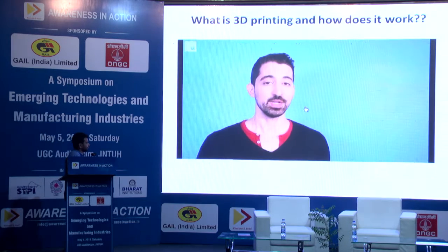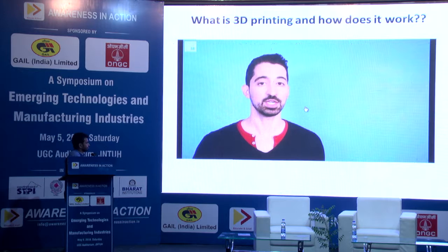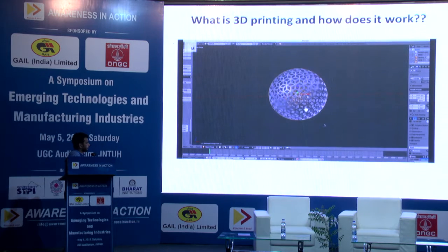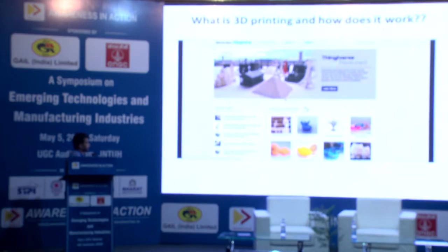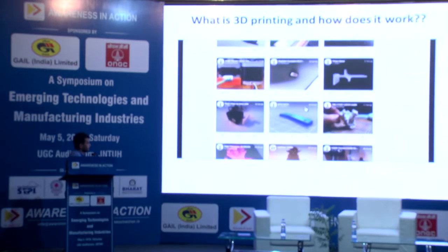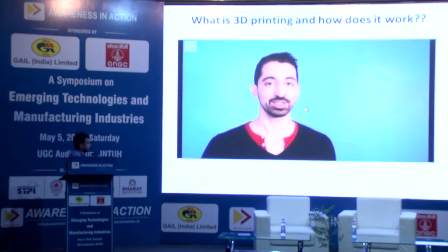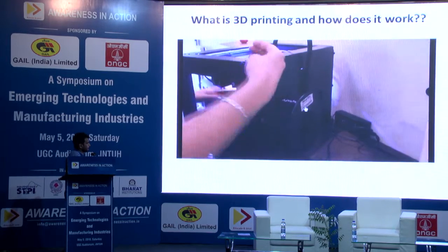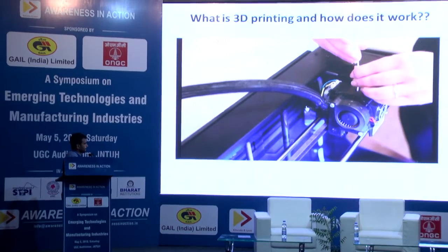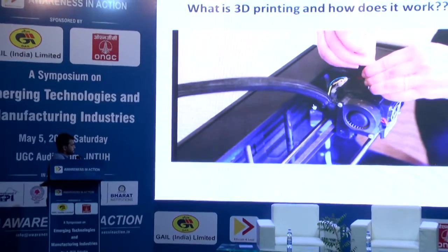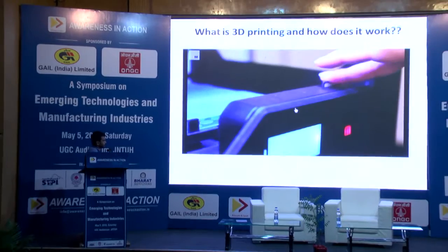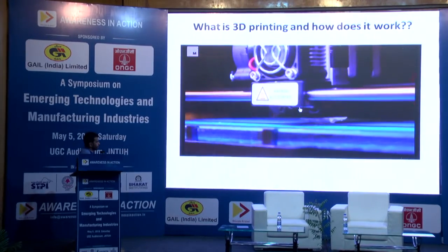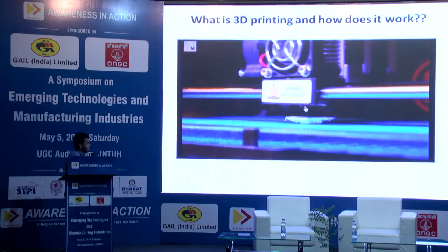The first step in 3D printing is to create a blueprint of the object you want to print. You can use modeling software like Blender to create your own designs, or you can visit websites like Thingiverse or Shapeways to find objects other users have 3D modeled. Once you have a finished design, it's time to send it to the printer. Some printers, like the MakerBot Replicator 2, have renewable bioplastic spooled in the back of the device, almost like a string. When the printer receives the data, it pulls the material through a tube, melts it, and deposits it onto the plate where it instantly cools.